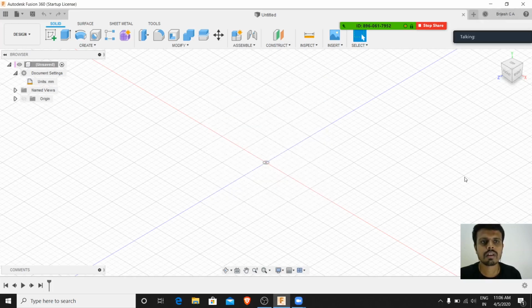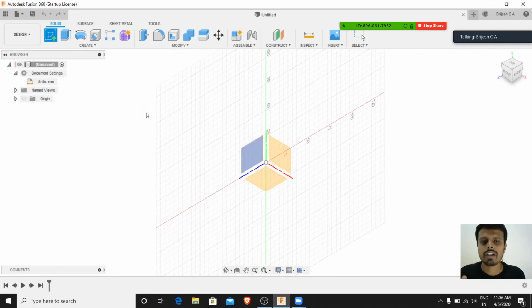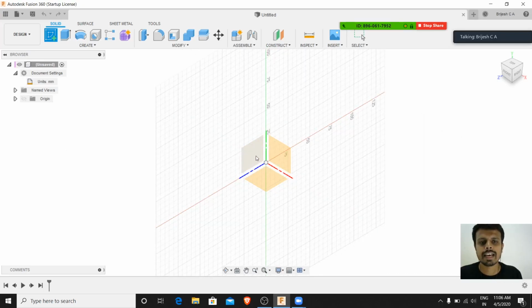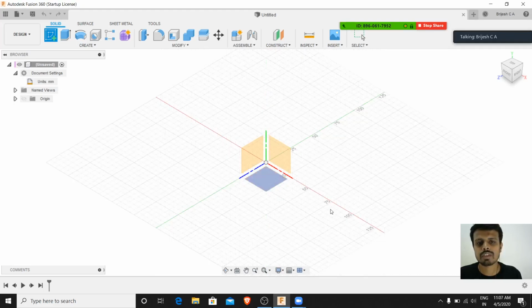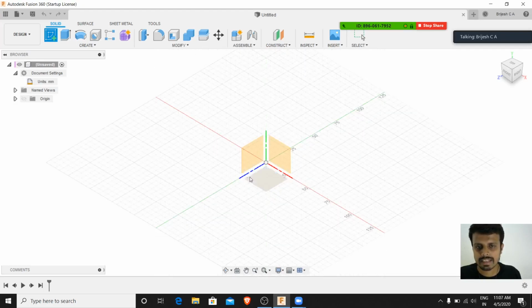Okay, cool. Now let's get started. I'm going to do exactly the same thing we did last time, and then we'll go further. So I try to create a sketch. Click on create sketch. We did not talk about shortcuts, which we're going to talk about in this particular session. What you see here is 3 dimensions, where I can choose one of the dimensions to start with. These are also called 3 planes. This is the bottom plane, the left plane, the right plane. Or if this is the y-axis, this is the z-axis, this is the x-axis and z-axis.